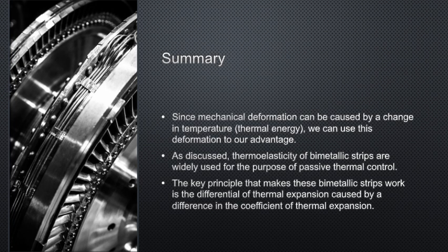And then the key principle behind these bimetallic strips is this difference in thermal expansion due to having a difference in coefficient of thermal expansion, and that causes this bending. This is all due to the thermal elasticity that we can see when we have a change in temperature.